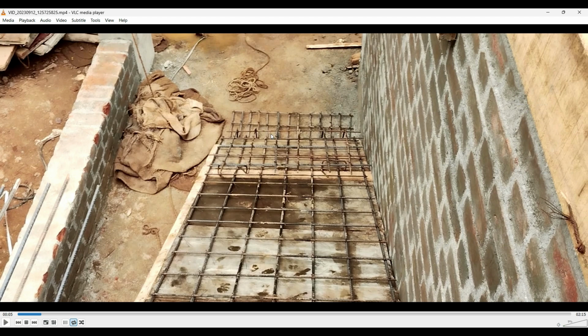Yeah. So if you see here, what is happening here? We don't have any plinth beam, right? Here we don't have any. We have not even dug inside. What are we doing? We are going to create a 6-inch slab over here with all this reinforcement, and we're just going to keep the reinforcement inside. Okay. So there will be a 6-inch worth of RCC concrete being done over here.